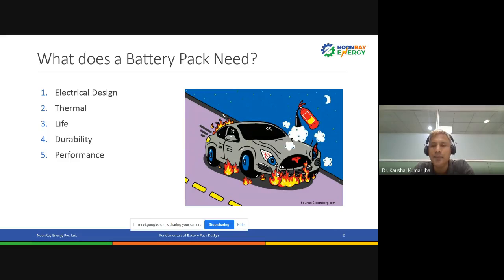I don't talk about hybrid here; I can say pure electric vehicle. So efficiency is 4 times higher. However, the energy density is almost 10 times lower than petrol and diesel. So on an average basis, you require a 4 times bigger pack than the petrol tank or diesel tank available currently.